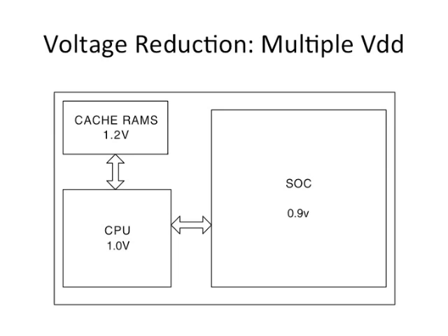It doesn't have to be fixed. It can keep changing during the course of operation. If I find that I'm running things slower, I can reduce the supply voltage, because anyway I don't need that much speed, so I can reduce the voltage and save. Besides, power of course goes down with reducing speed, but I can save energy also by reducing the voltage. Right? The CV square helps to reduce the energy.